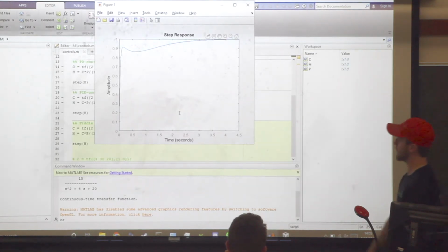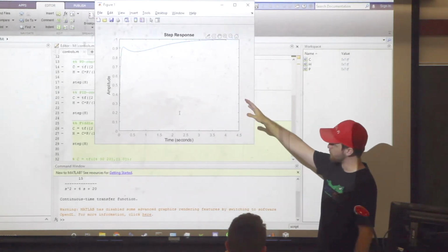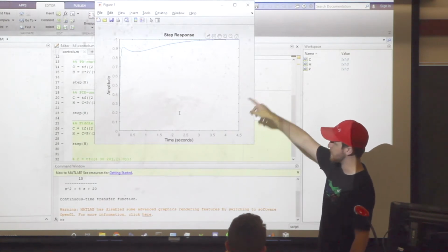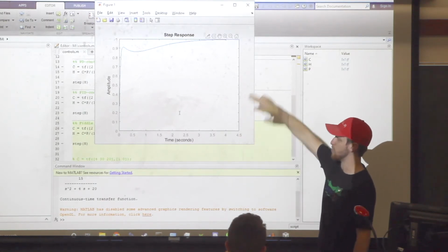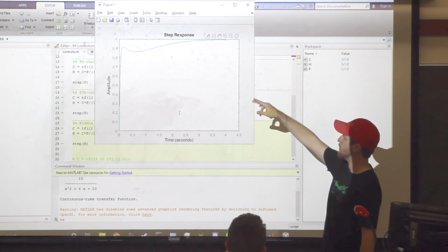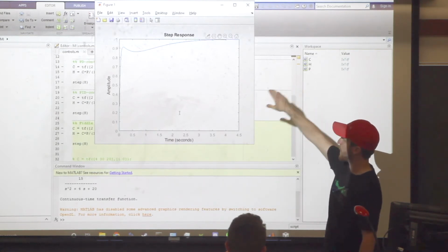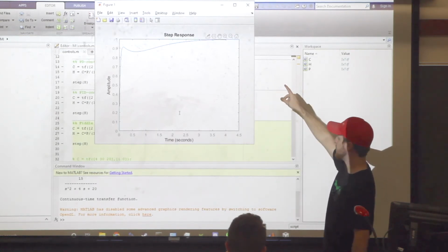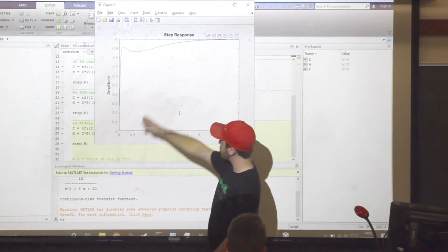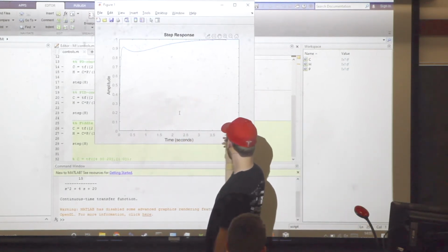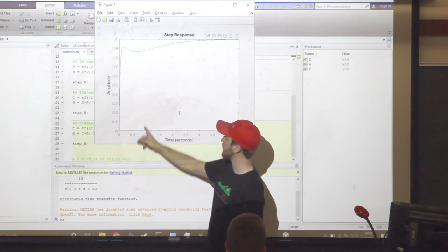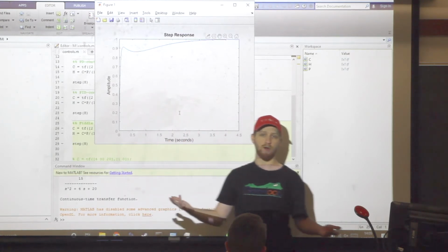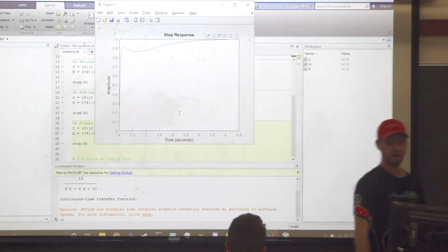And you'll see it goes up. It's a weird little sort of dip. That's from the derivative term saying, hey, we're approaching too fast, slow down. And then it slowly comes back up, and then you finish at 1. You get most of the way there pretty quickly, but maybe not quick enough. After a second, you're at 0.9, so that puck may have just gone past you.